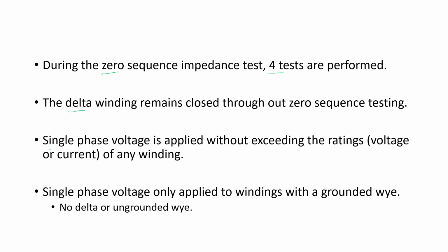Then single phase voltage is applied, without exceeding the ratings of any winding, because sometimes the circulating current can exceed the withstand of one of the windings.